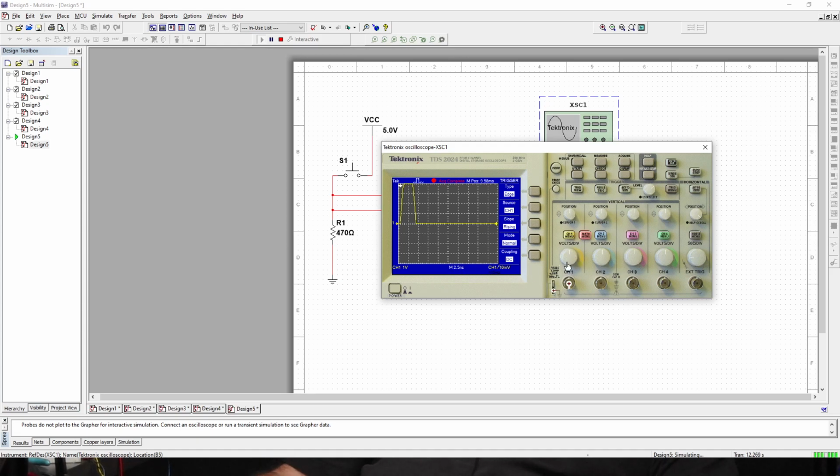Now we are operating channel 1. So here's the positioning. See the vertical position of channel 1. So we can control that. We can select that. So now you see this little triangle here, this little arrow. That shows the 0 value of what we have. Right? Now, we can just bring it right down, so we could see the whole pulse. Can we bring it to the very bottom of the screen? Yes, the bottom. But let's just bring it one higher, so we could see things nice and clear.